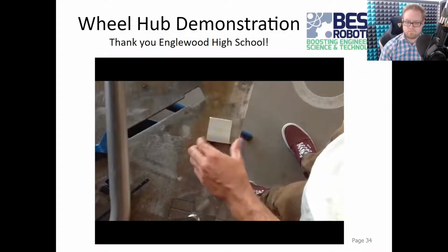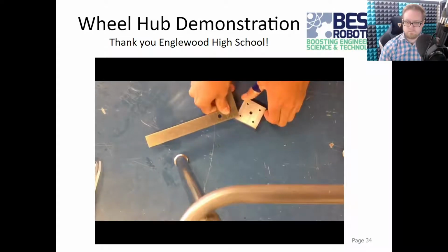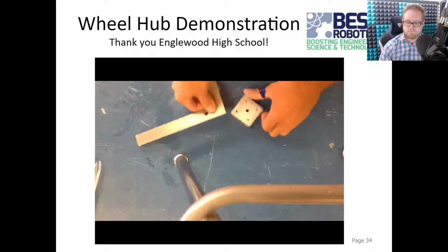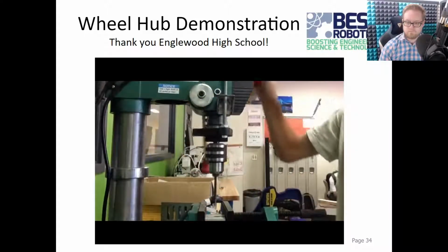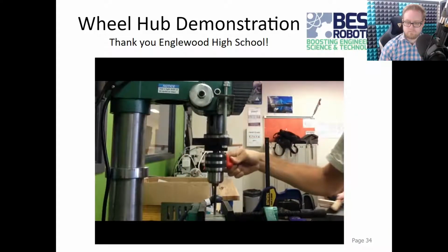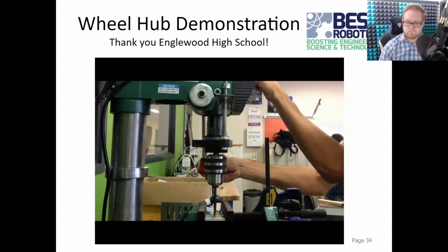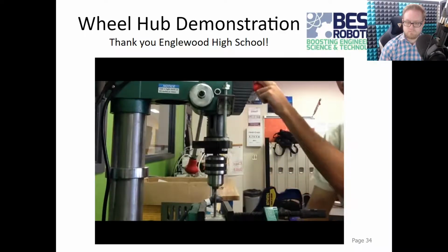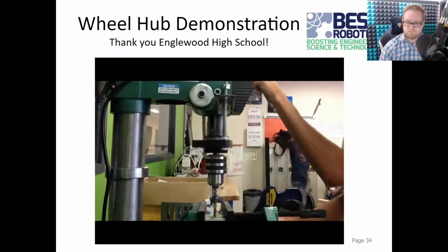For the holes on the corner, you're going to want to mark in a 1/2 inch on each of the 4 corners. Where you drew that X a moment ago, you're going to want to drill directly into the center. You want to make sure that this hole is drilled all the way through. Apply drilling fluid if needed.